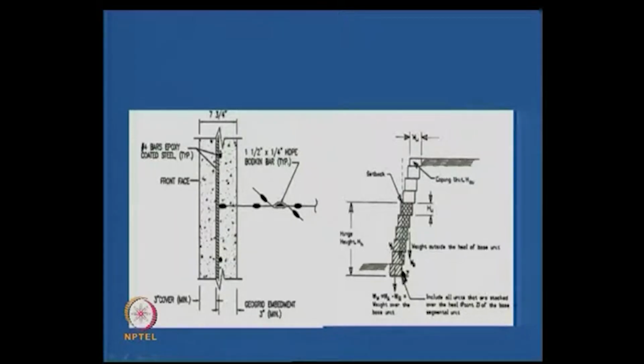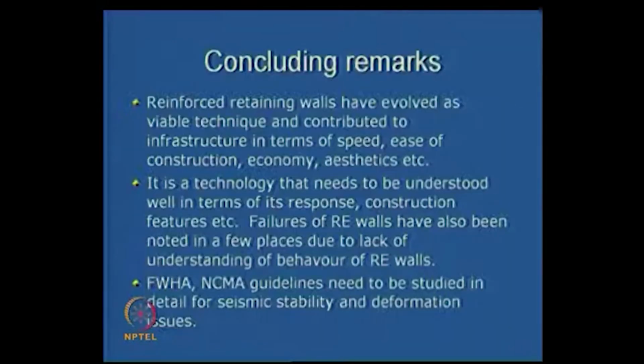And the second thing was, as I was mentioning about segmental wall construction, you have a number of blocks like this, 1, 2, 3, 4 like this. When you have this type of material, they have to be properly locked. There is a setback that was given, but there is a procedure that one needs to follow. Otherwise, the equilibrium of each block, the forces and the anchorage are affected. Otherwise, there is a possibility of total collapse, which we saw in failure mechanisms also.